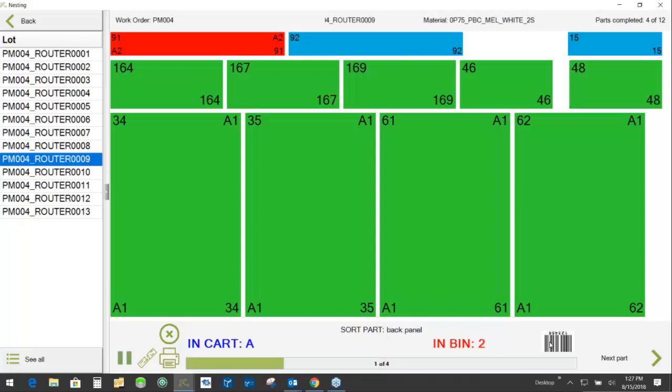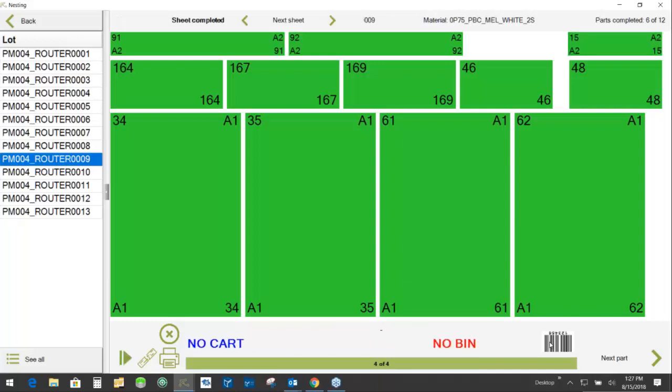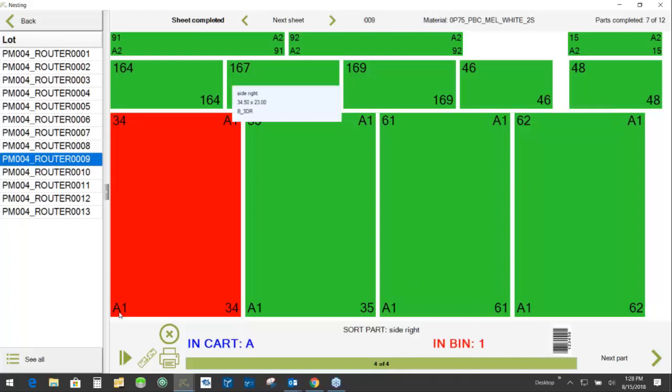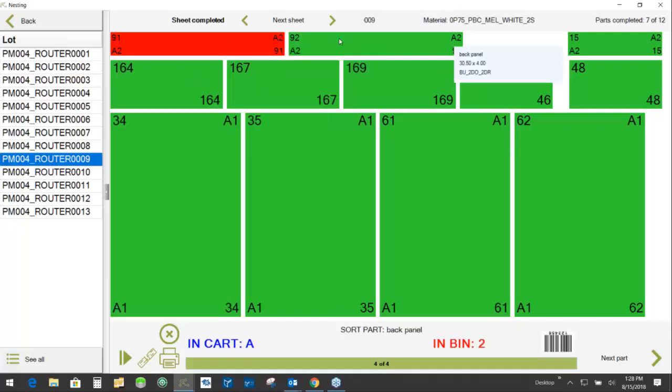So what does that mean? Well, coming off the CNC, many people are going to go to edge banding, horizontal bore, whatever next operations are for you. And so we can either group by like edge material, or we can group by part type. So imagine that the operator here has a nice symbol. We can see that very first part we were dealing with is telling it to put it in A1. And so all of the common edge bands are going into that grouping so that it makes it easier for the edge band operator to be set up and to run all of those in an order. And then we have different materials for A2 that are happening as they come across.